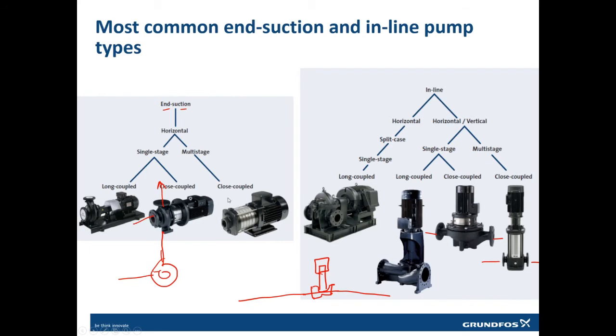more than one stage. We have long coupled, close coupled. In inline we have horizontal, vertical, we have split case. Split case means, if you see here, this part of the pump can be opened. So if you need to change anything, wearing, shaft seal, bearing, anything, you don't need to decouple the pump or the motor. You just need to open the casing and do whatever you want to do here.